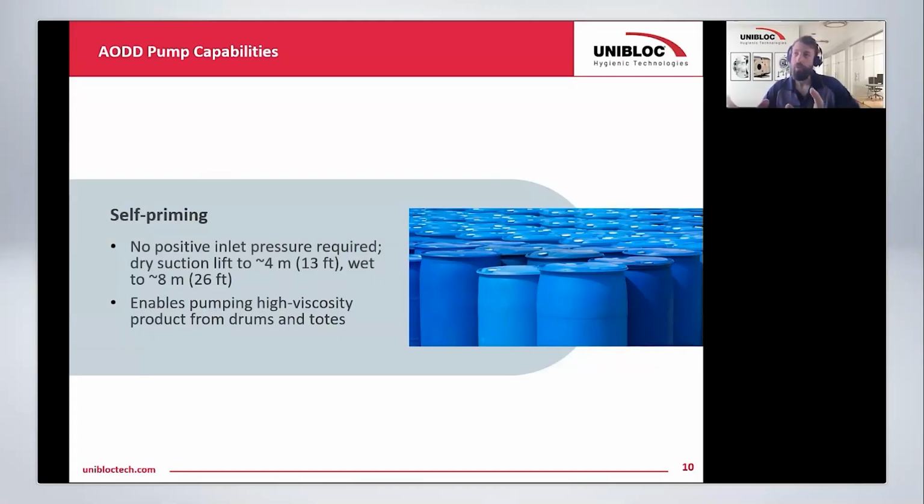And one thing to note, kind of a little tip on pulling suction, is that there are more limitations on how much a pump can suction lift than how much it can pump. So it's best, when you're sizing a pump that's going to be doing some suction, to size it for the suction more so than the discharge.